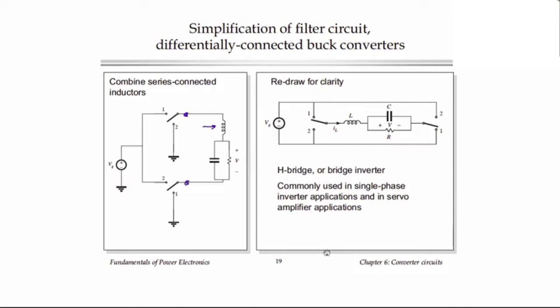So to drive the motor in one direction, we apply a positive voltage, that's DC. To drive it in the opposite direction, we apply a negative DC voltage. And so we can do that with a circuit like this as well. We might, in that case, actually replace the whole RLC network simply with a DC motor connected differentially between these terminals. The self-inductance of the motor winding takes the place of this inductor, and the inertia of the shaft replaces the capacitor.